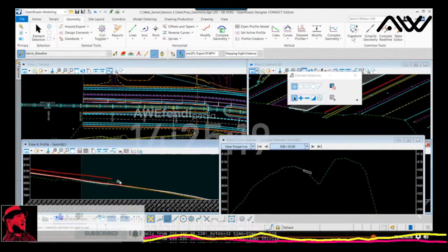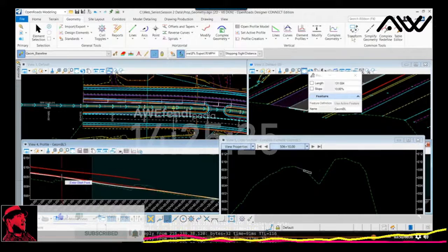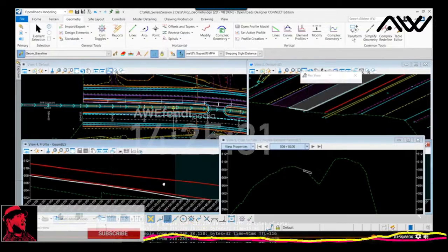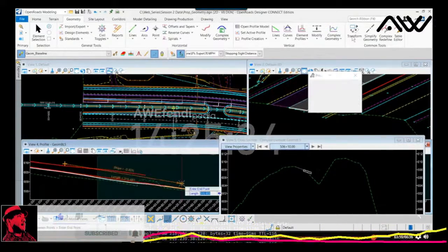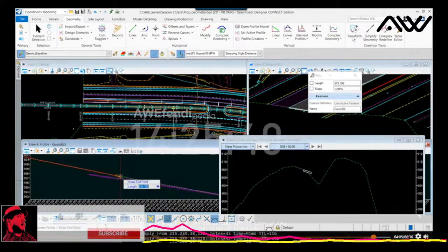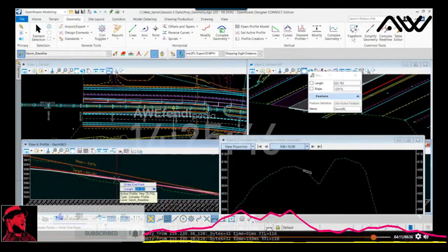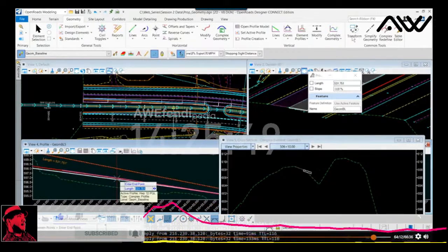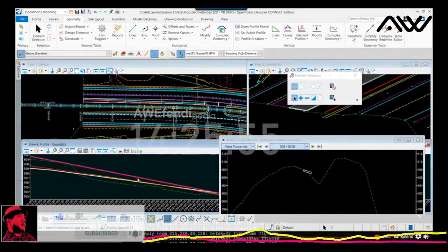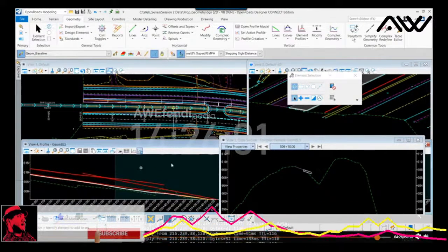To do that, I'm going to go back. I'm going to use profile line again. I'm going to just take and draw a tangent area. Again, a straight vertical line. Now I'm going to use the MicroStation tangent snap. Let me get this view proper. And I'm going to be sure and select a tangent location to my PGL, okay? And data point. And so now I have a taper that's tangent again to that vertical curve, and I'm going to just insert another curve between my elements.